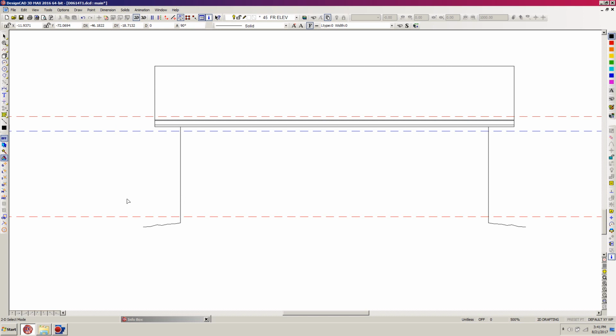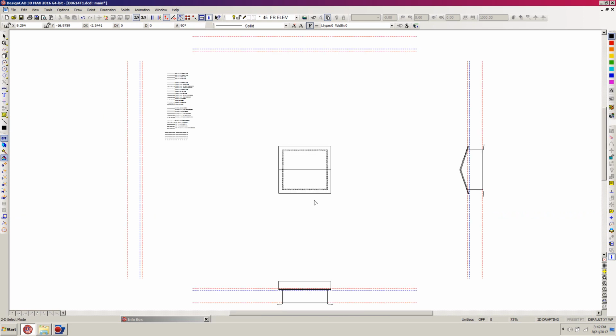So I'm going to hit V for vector, and I'm going over here to our intersect 2 also and clicking on that, and then clicking near this line and then this line, and hit H for orthogonal mode. And so now it just comes on over. I can just right click to this point right down below here, and now I just hit my scroll button and it's activated. So there's our floor line. We'll be removing this portion where the garage door is later. Control W, and that concludes Lesson 10A, the beginnings of our elevation.